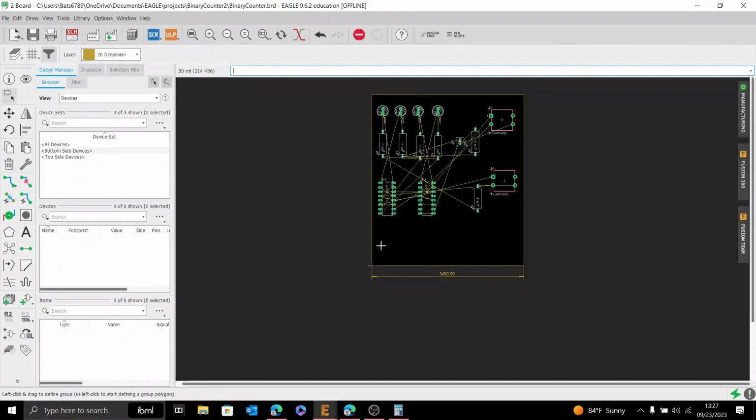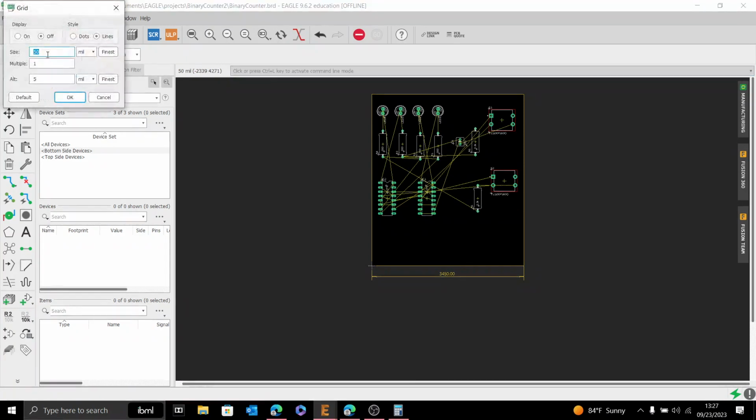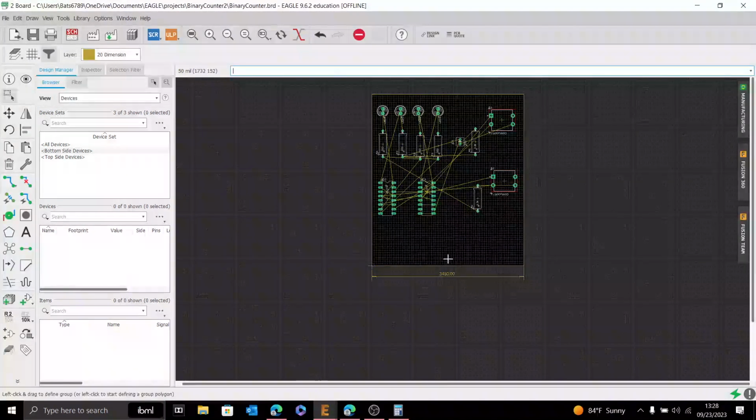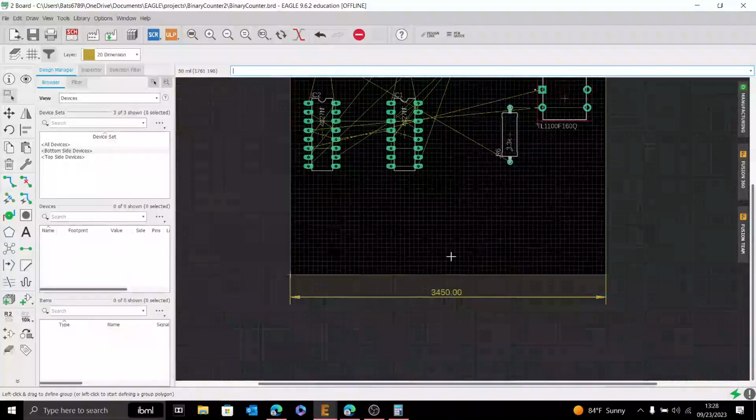All right. So as I mentioned, we have that little power supply over there that I had to make by hand. I already got these measurements once, but you can imagine how I use that measure tool with the Adafruit schematic in order to get all these numbers. So let's turn on the grid, and I'm going to set these to 50 mils because most of those components were in 50 mil spacings. I'm going to display it. Where's my PCB board?